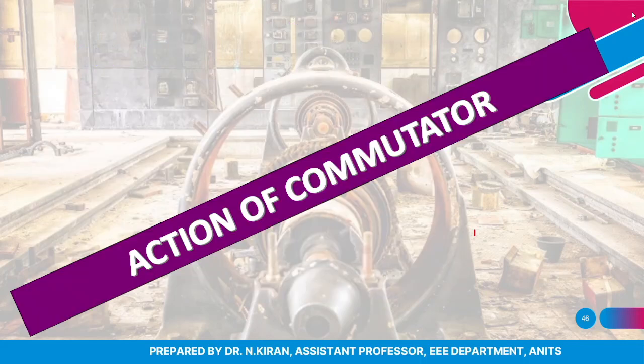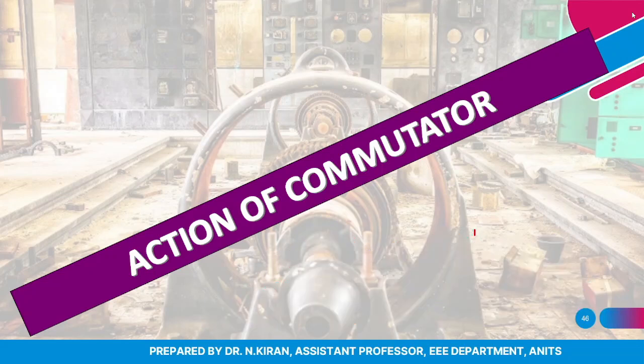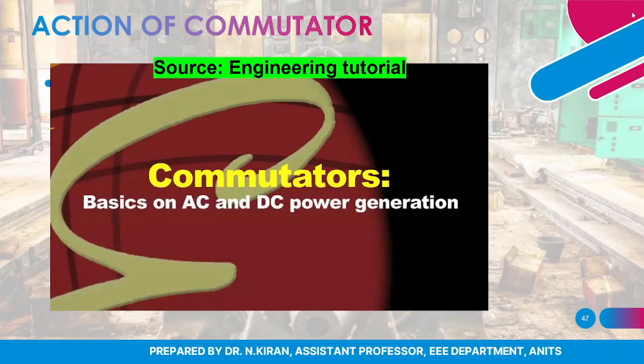As I told you, I need a commutator, because even though this is a generator, my output is alternating in nature, so I need to convert this into a unidirectional EMF. So there comes my commutator. Before we see in detail the action of the commutator, I just want you to listen to a small video regarding the commutator.